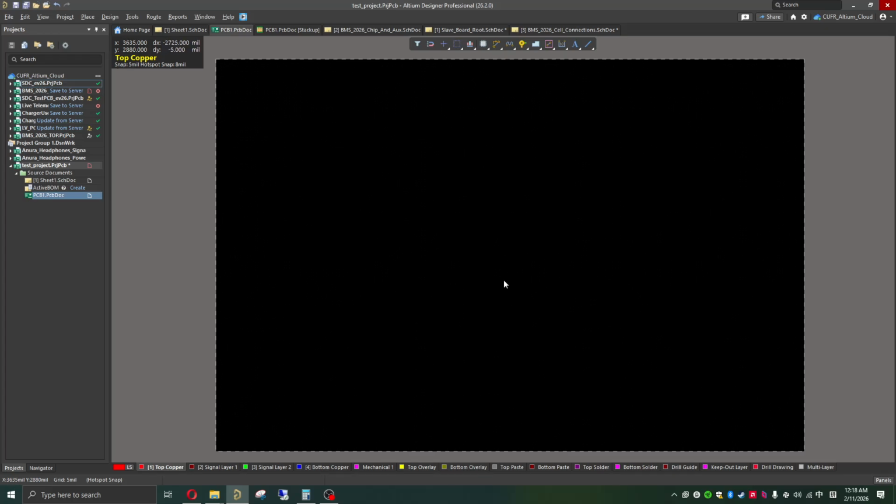All right, pretty good. We're at a pretty good starting point. I want to explain what some of the layers are. I'm not going to talk about all of them necessarily, but just to get you started. The layers that are copper, or your conductors, are usually the first 4, or the first 2 or 6, however many you need. That's our top copper, our 2 internal copper layers, and then a bottom layer. So this is where we'll be making most of our electrical connections.